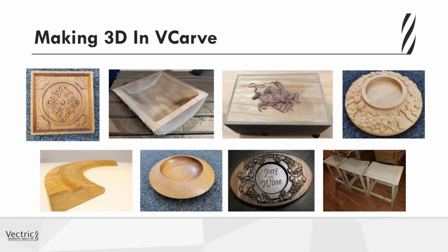In this demonstration, we'll be looking at many ways of creating 3D in VCarve. We'll be demonstrating many different methods in the software, from looking at importing 3D data and how we can alter it, to looking at toolpath strategies that enable us to machine 3D parts.